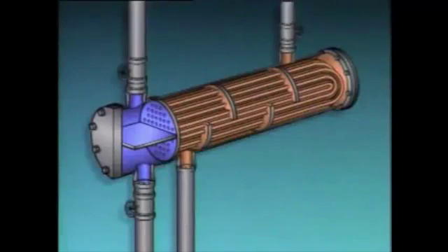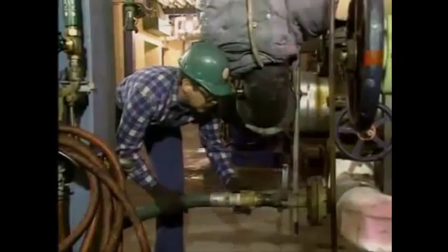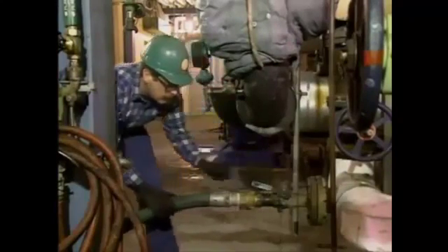On the heat exchanger shown in this example, the shell side has no isolation valve on its outlet. Some shell and tube heat exchangers have an isolation valve on this outlet. With those heat exchangers, the isolation valve must be shut to completely isolate the heat exchanger. After the isolation valve is shut, the operator opens the cooling water drain and vent valves.